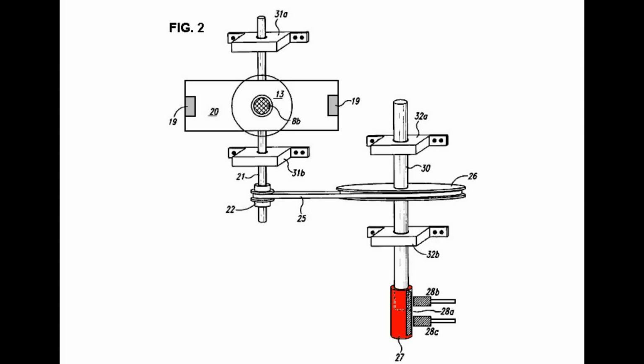As rotor 20, which is attached to rotor shaft 21, rotates, each pole 19 respectively comes in momentary monopole interface with pole piece 18B. The polarity of pole piece 18B is constant when electrically magnetized. Rotor shaft 21 has rotor shaft bearing blocks 31AB attached to it for stabilization of rotor shaft 21. Attached to rotor shaft 21 is drive pulley 22 with timing belt 25 engaged with it.